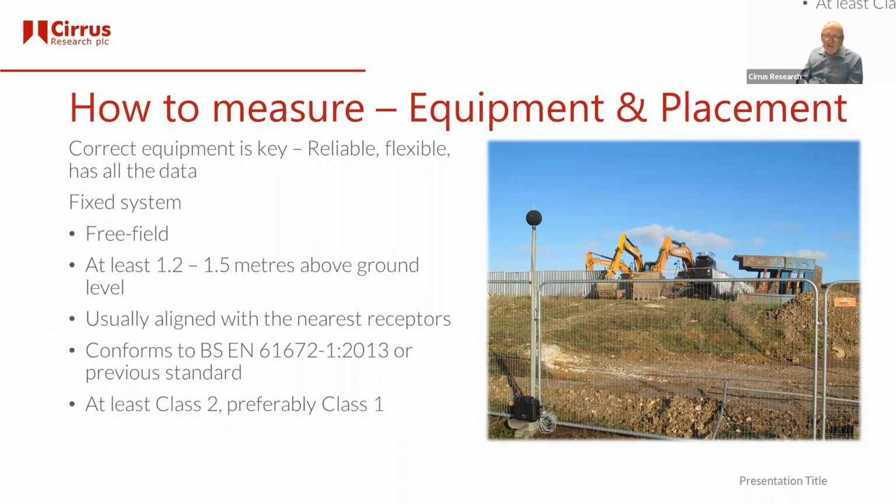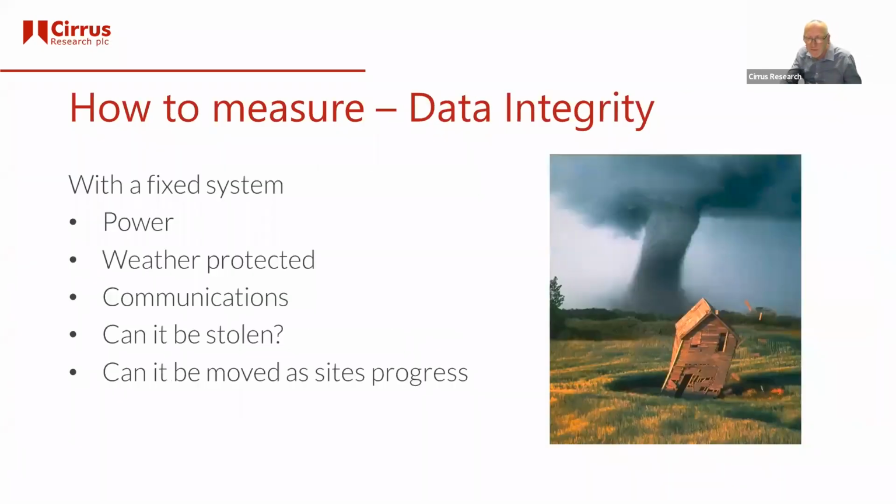We've mentioned the standards for the sound level meter. This is the latest one, 61672. At least class 2, and I would say preferably, and you might as well just do it in all cases, class 1 sound level meters.